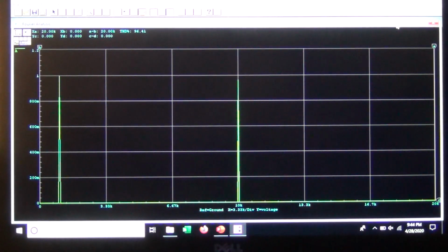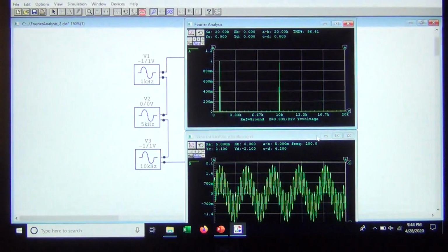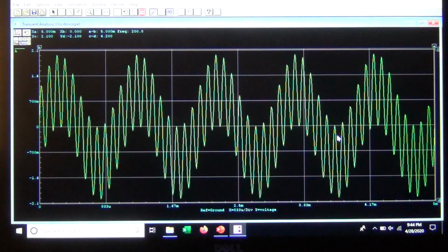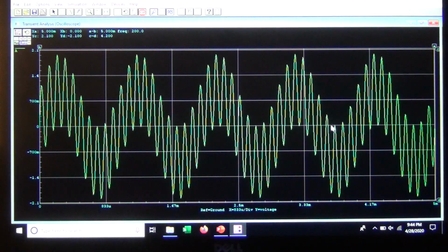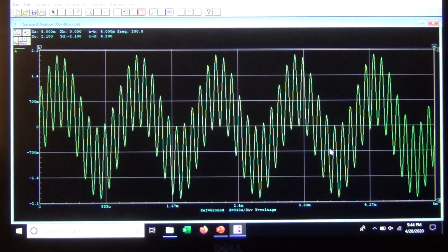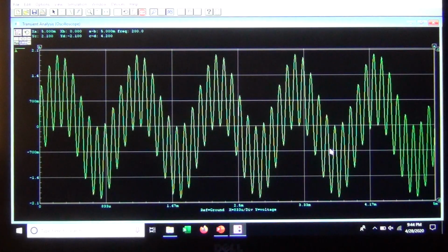I'm going to get rid of this, I hope, and bring up the time domain. And now with this one, you can really see the two frequencies there. The sine waves, which happen very rapidly, from here to here for instance, is the 10 kilohertz signal, and we can see the much lower 1 kilohertz, or 10 times lower in frequency, signal here. So it's not too difficult to ascertain what frequencies are in this signal. Again, if I went from tip here to tip over here, I would find 1 kilohertz. And if I go from tip here to tip here, I'd have 10 kilohertz.